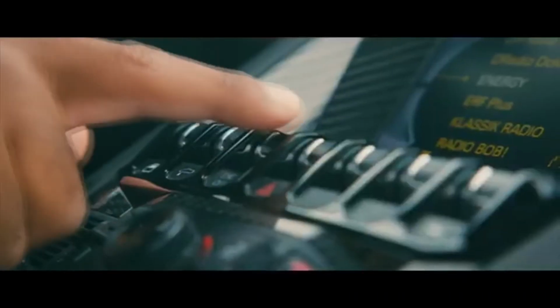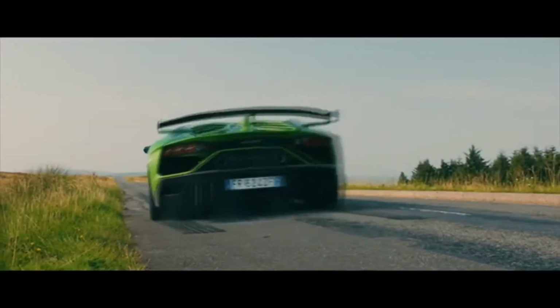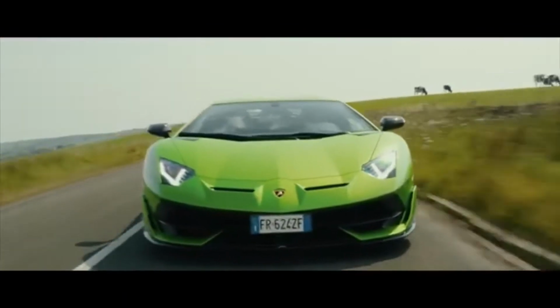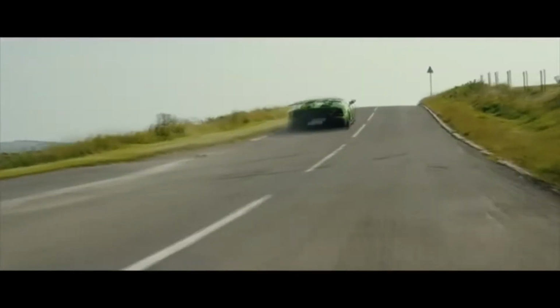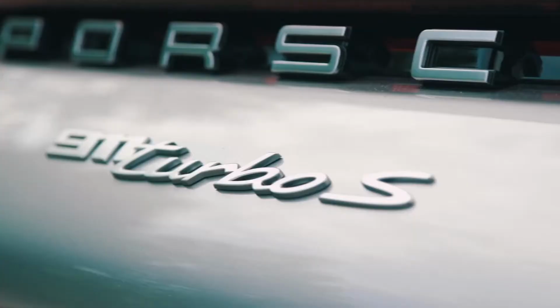You basically put the car into Corsa, which is a special all-out sport mode for Lamborghinis, turn ESC off, which takes stability control off, and turn off traction control. Then you put your foot on the brake, floor the accelerator, and then let go of the brake after a second or two, so the car can launch and accelerate really fast. The same goes for the Audi R8 V10 Performance and Porsche 911 Turbo S.